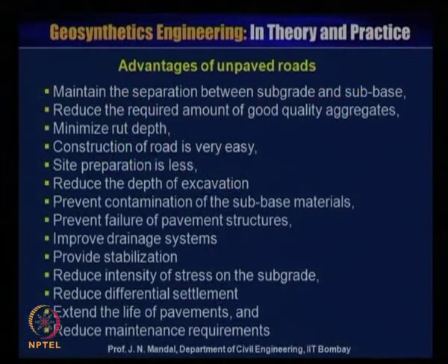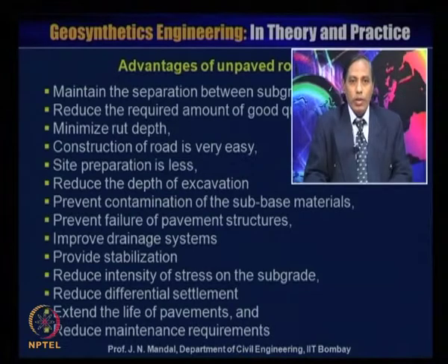Maintain the separation between the subgrade and the subbase. Reduce the required amount of good quality aggregate. Minimize the rut depth. Construction of road is very easy. Site preparation is less. Reduce the depth of excavation.